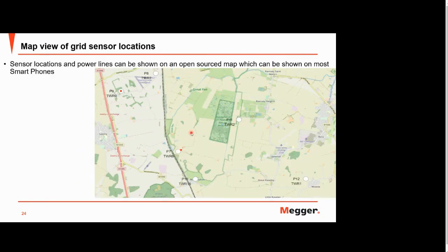We also put in all the details of the sensors, like the GPS coordinates and the KMZ file of the network. So whenever a fault happens, the customer can easily open Google Maps and has a much better idea of where to go, rather than just doing patrolling. Those sensors are also capable of sending SMS. If you have a dedicated app, the team in the field gets an SMS on their mobile saying this is the location where the fault happened and this is the sensor name, and also an email notification to the authorized list of names you have shared in the software. So you get email as well as SMS notification whenever a fault happens in your network. The team can then directly use Google Maps with the coordinates where the sensor has been installed and go to that particular location.